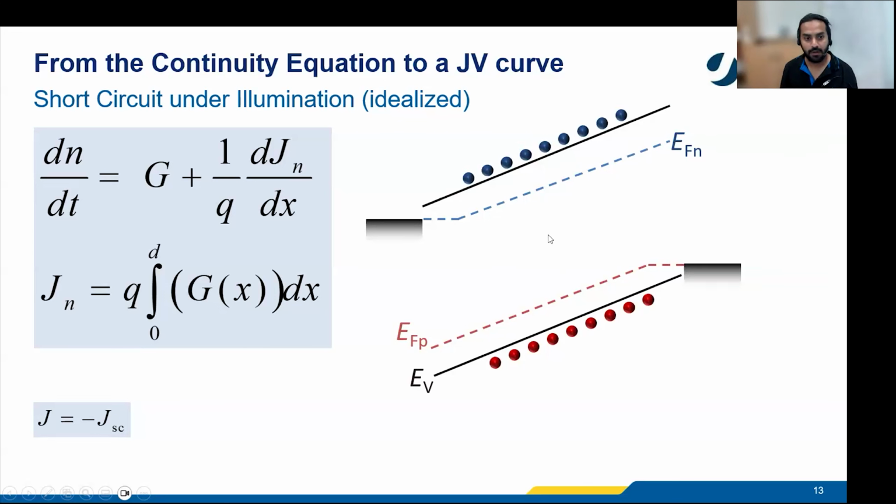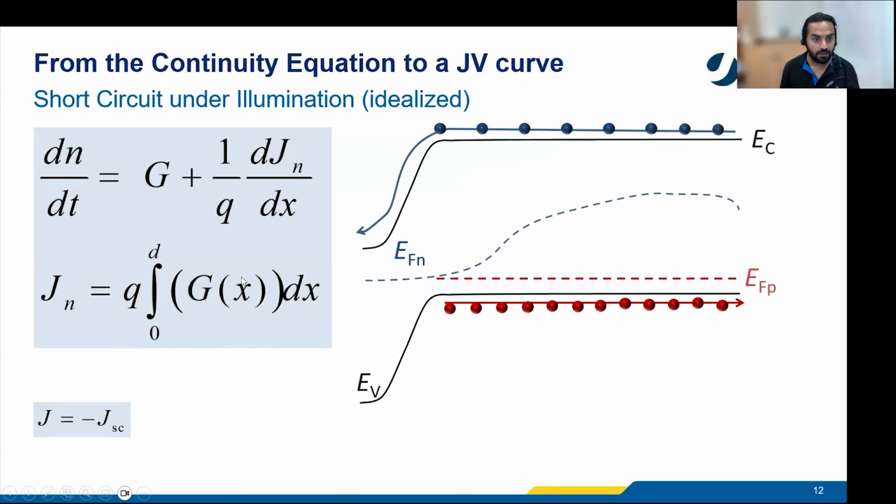And again, moving from a doped sample to a kind of PIN situation, here you would have a voltage dependent collection again. I'd just like to note that since this is an idealized case, we just use this equation, but in reality, there is a collection probability term that has to go in here as well. That again depends on the diffusion length and the surface recombination terms.